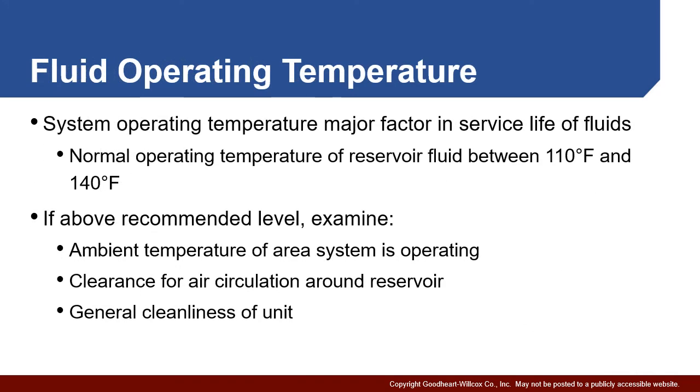One of the key things you're going to have to maintain is the operating temperature. As we've indicated, we want our oil to be somewhere between 110 and 140 degrees Fahrenheit. This is generally going to be measured in the reservoir itself. And why we're so concerned about it is this temperature has got a lot to do with the service life of your fluid, but also the service life of your components.